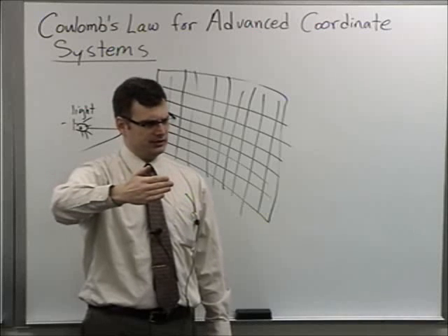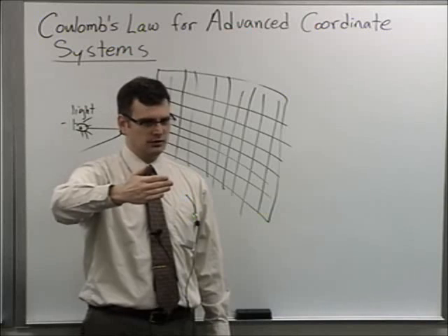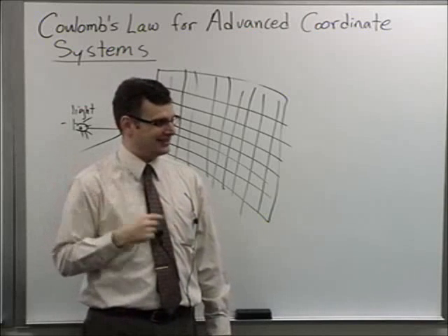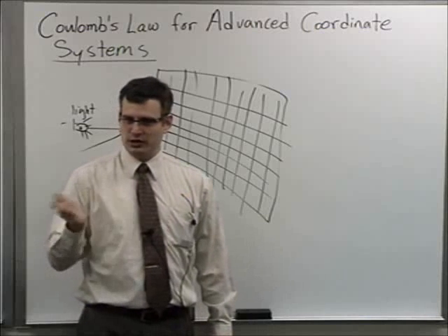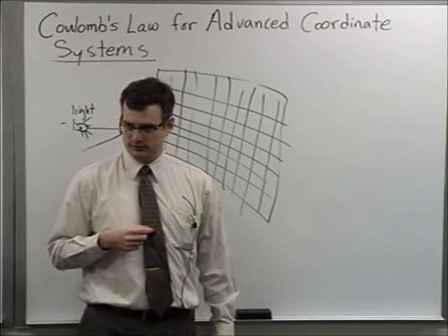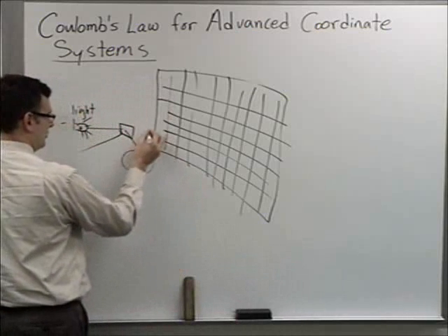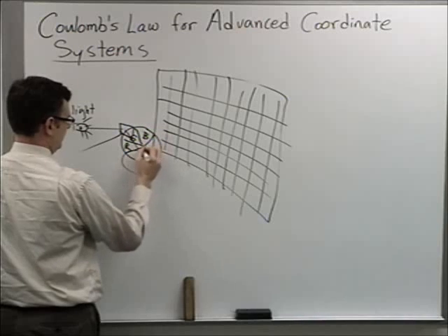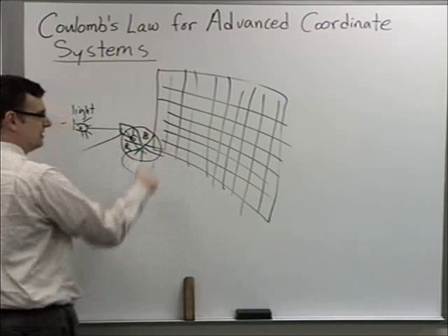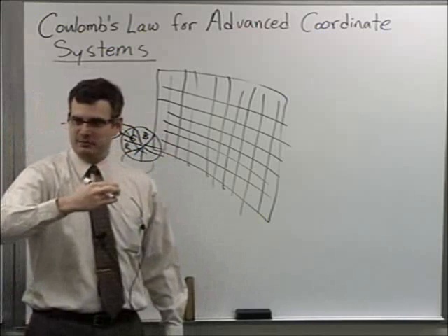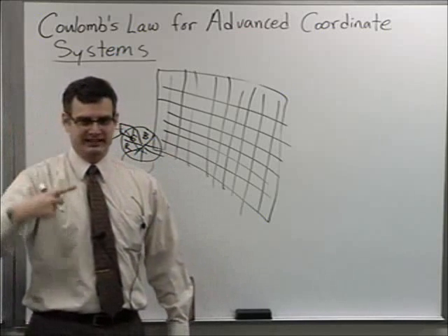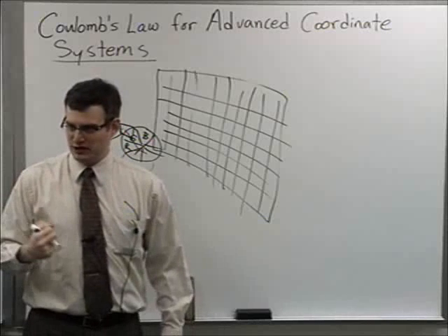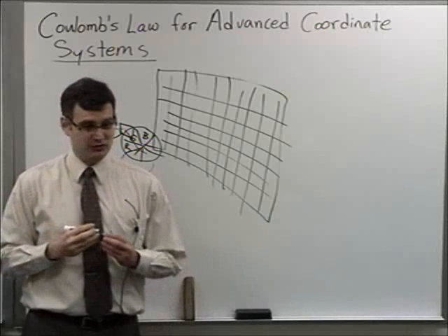What if you want a gray pixel? Well, you oscillate it a couple times, depending on the intensity. That's how fast you can do these. What if you want a color pixel? Well, it turns out that there's a little color wheel here that has red, green, and blue, and it repeats itself a couple times, and it just spins around. So if you synchronize your mirror flipping with red, green, and blue, and you're updating the image fast enough, your eye blurs the combination of red, green, and blue together. It actually makes for a very nice image.